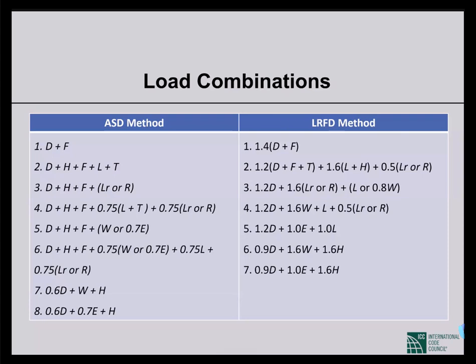For strength design, we have a set of load combinations, and for allowable strength design, we have a different set of load combinations, but these are the same for concrete and steel. So this is very important. And since you have already covered the concrete part, you are familiar with the load combinations.